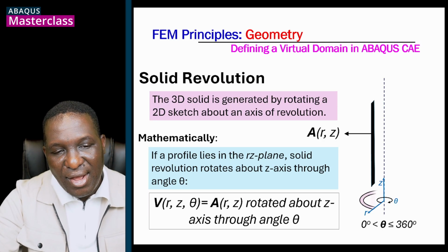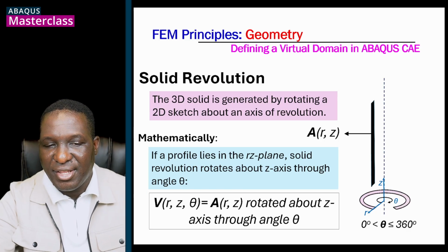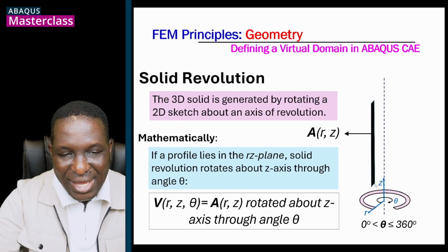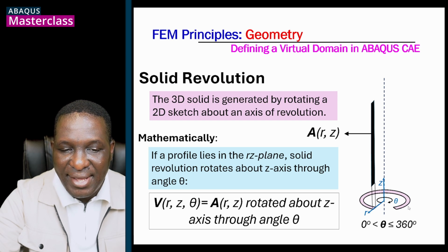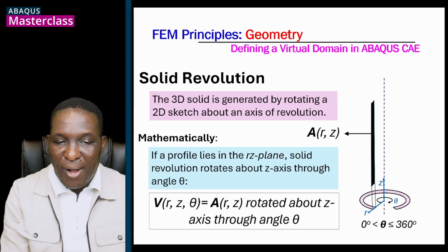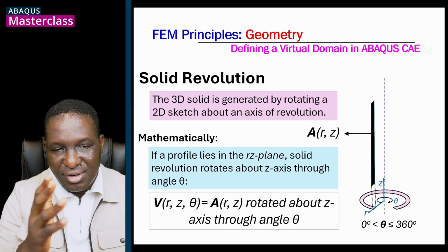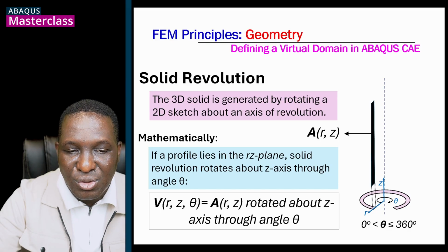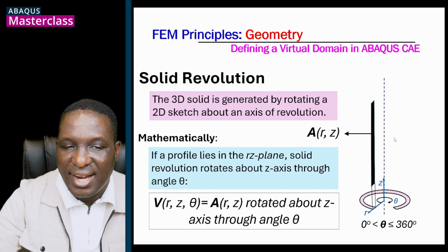And then the next thing we have is the rotation about the axis. So imagine this space, you need to rotate it 360 degrees to create that base. That forms the base of the new geometry, similar to what we did with extrusion. You've got the base, but as well, because it's an RZ reference frame geometry, you also need to rotate. While that rotation is happening, it's also happening longitudinally around the Z axis.